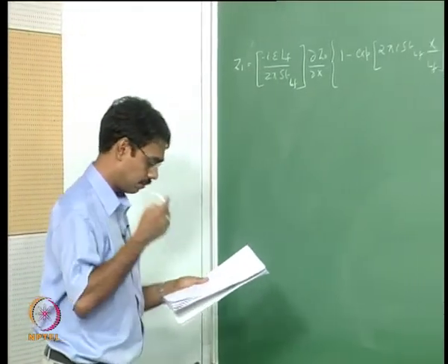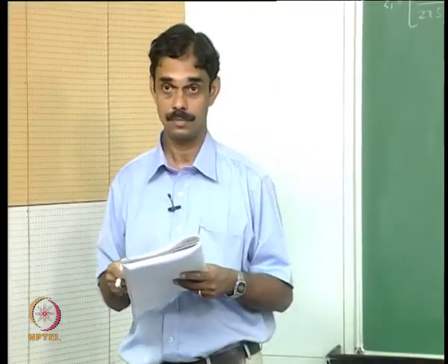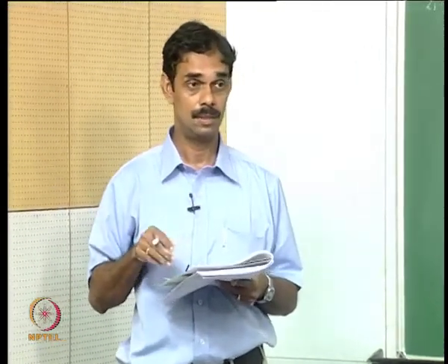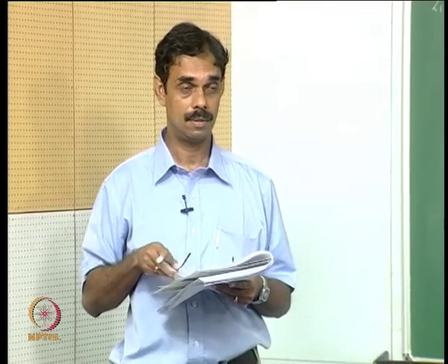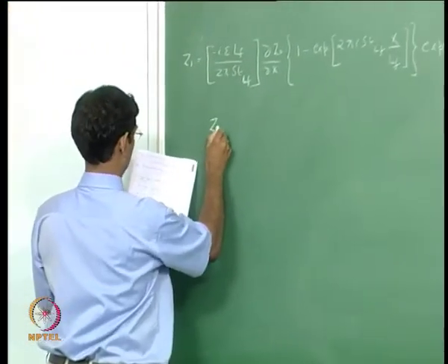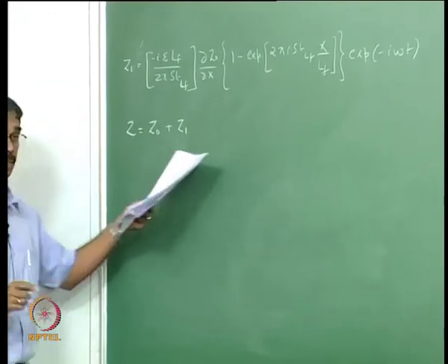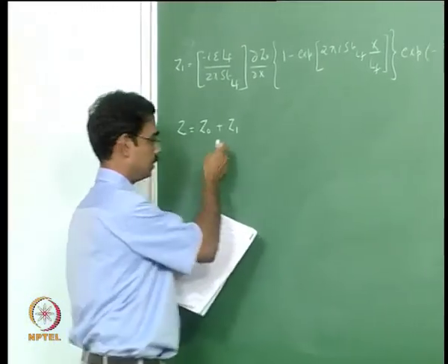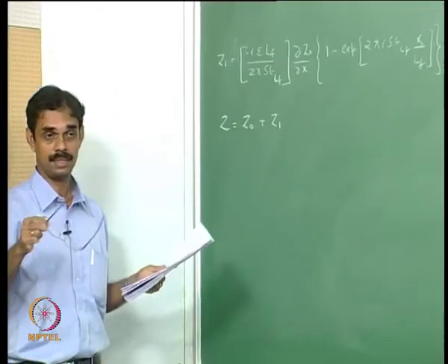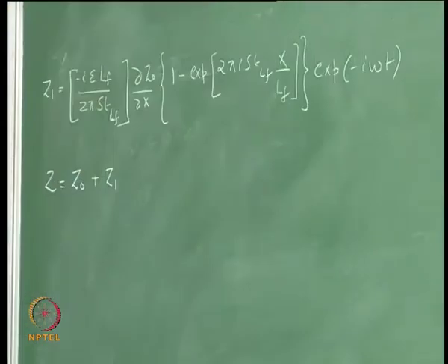So to find the flame sheet, how do we look for the flame sheet or the flame surface, whatever? We look for the stoichiometric surface, and that is where we have the flame. So Z is Z0 plus Z1, that is the instantaneous value. So Z is Z hat times e power minus I omega t, but you have to take the value at that particular instant.